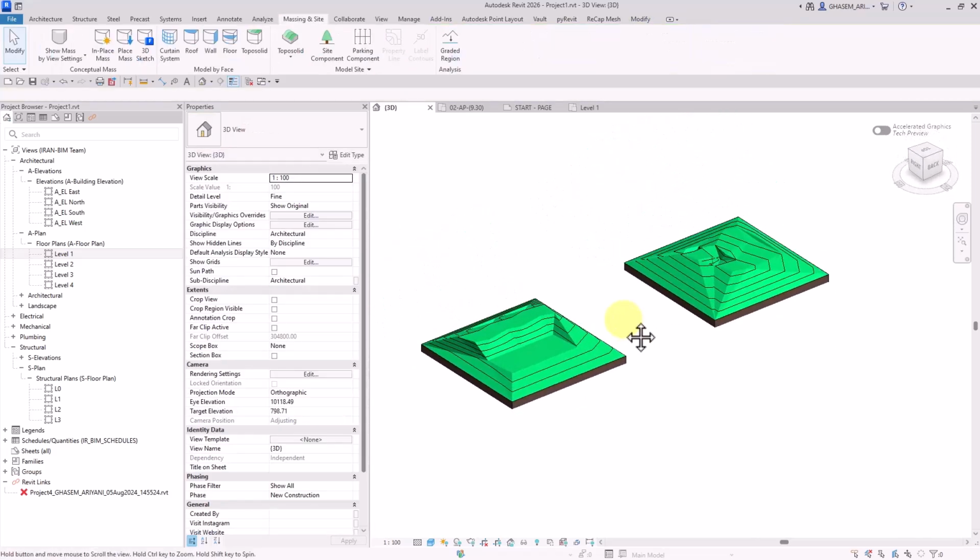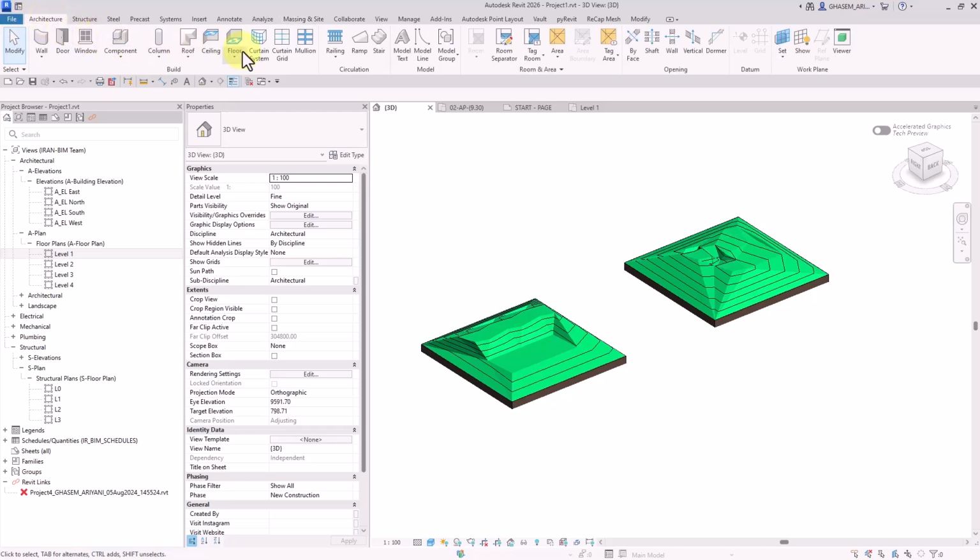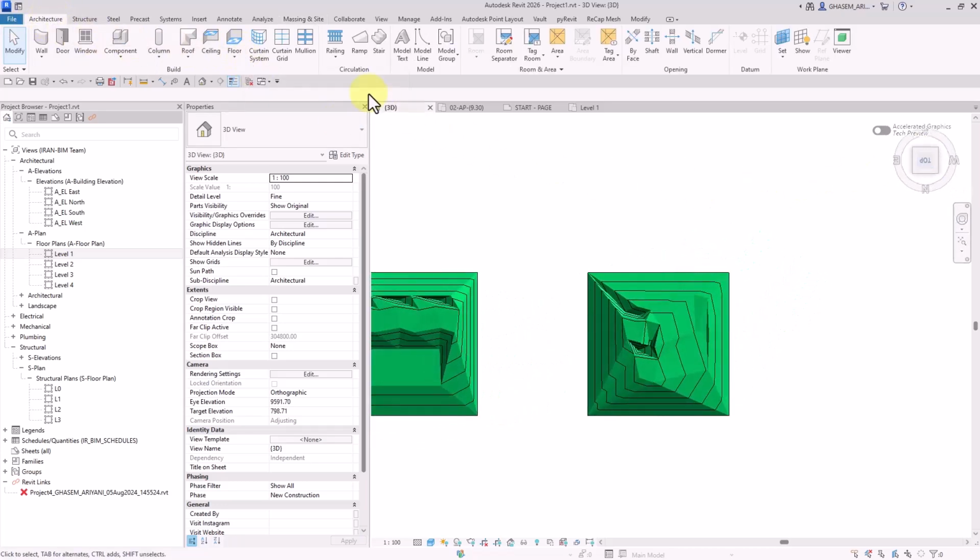Now guys, remember, we basically use this technique when we have some points and vertices for creating, we can say, topographies or basically slopes in some floors. And then, let's say we want to use those topographies or slopes in another place, in another area. In such cases, you can use this technique to add a lot of pace to your works. And again, guys, as I mentioned earlier, this interesting technique works on Toposolids, floors, and roofs.